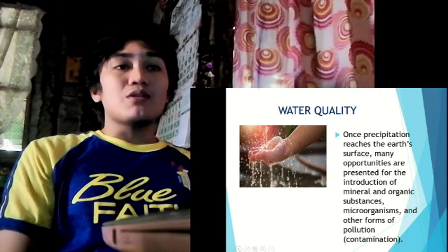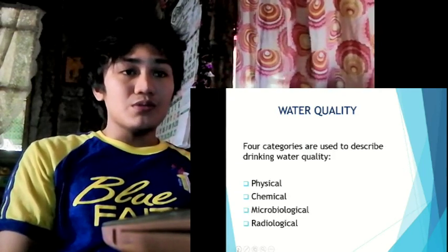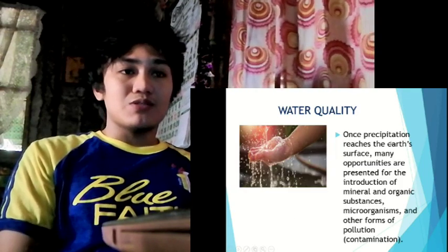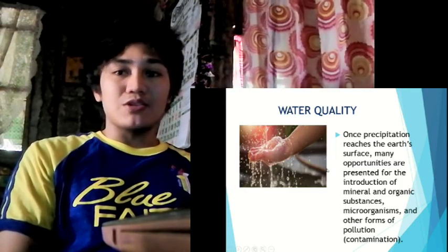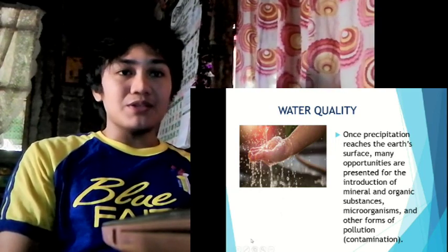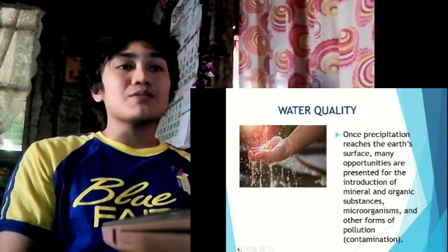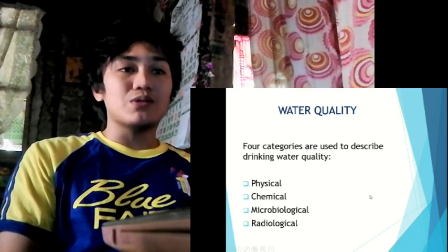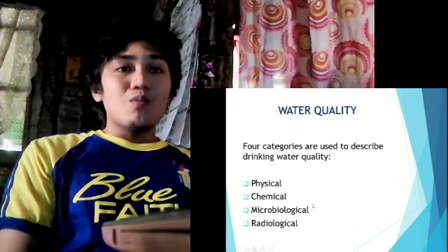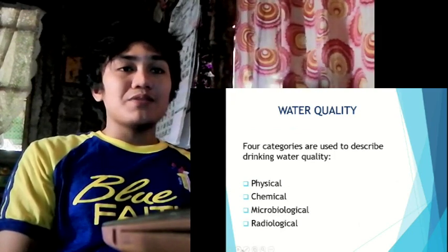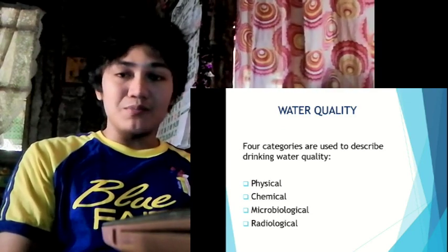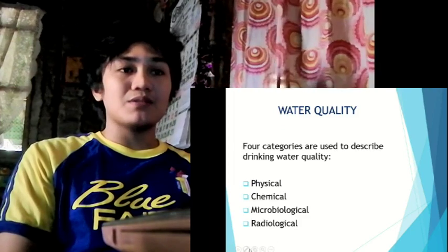When water runs over or through the ground surface, it may pick up particles of soil. It is noticeable in the water as cloudiness or turbidity. It also picks up particles of organic matter and bacteria. As surface water seeps downward into the soil and through the underlying material to the water table, most of the suspended particles are filtered out. This natural filtration may be partially effective in removing bacteria and other particulate material.